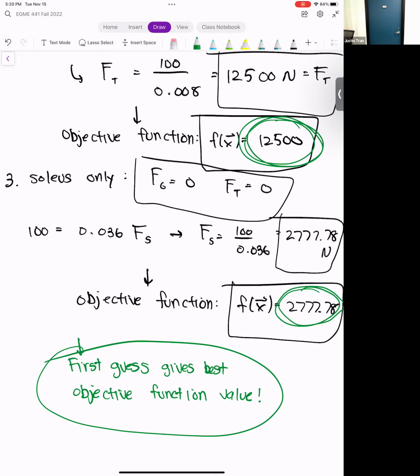For 4A, can you help me figure out one again? This is a fix, and this is a pin. So the rotation is free on this one, only the transverse is constrained. So we have D1Y and theta 1 both 0.